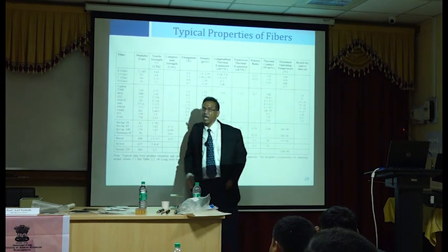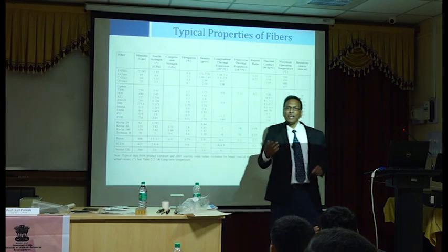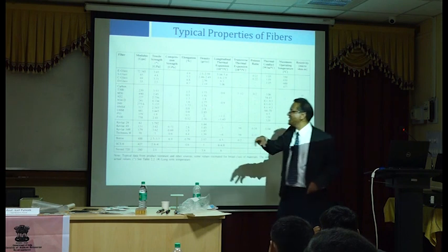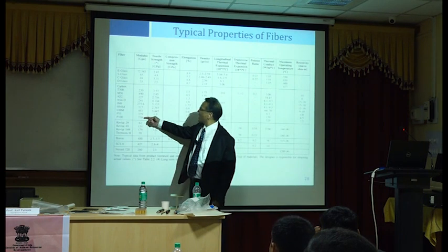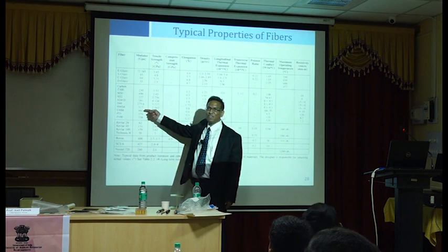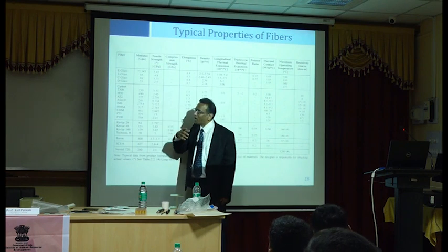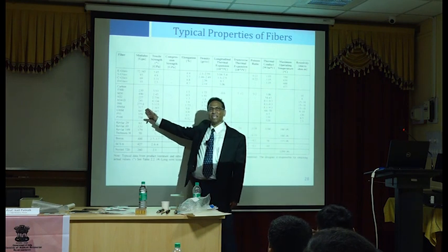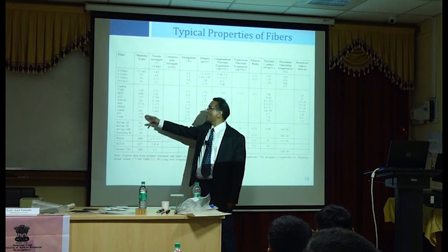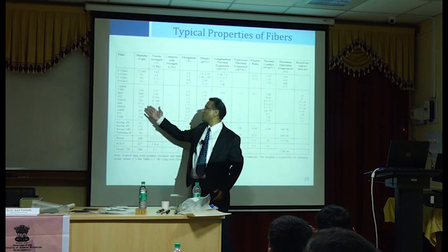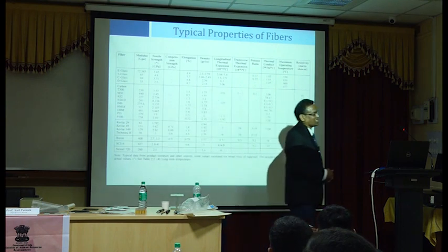It's a very, very high modulus, right? Again, compare it with steel. Steel is 200. This carbon, you can get even 758, 441. It's stiffer than steel. So based on my statement just a couple of minutes back, these are very good candidates for structural application. Only problem is they are very, very expensive, so they cannot come to the civil engineering market because of the high cost.